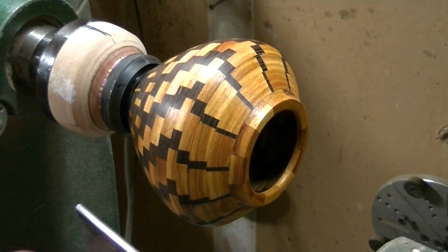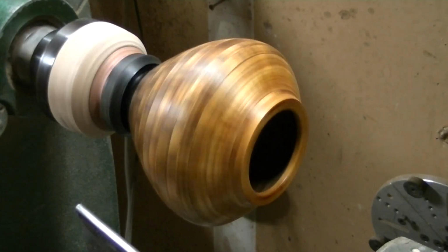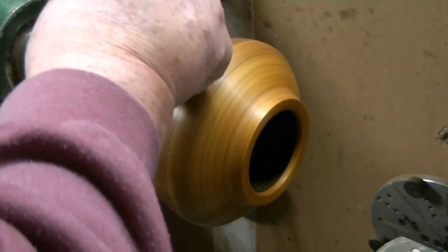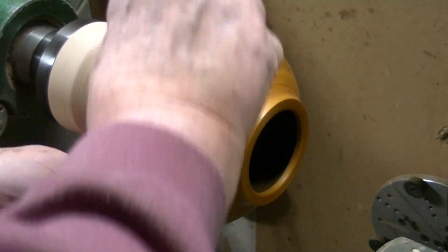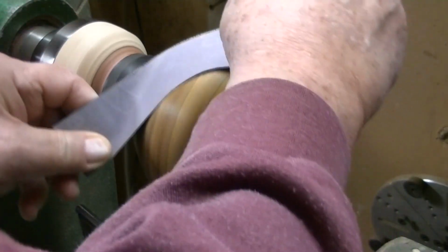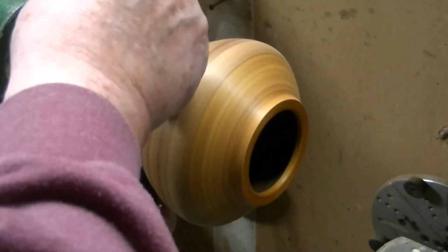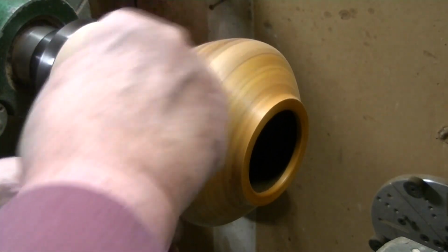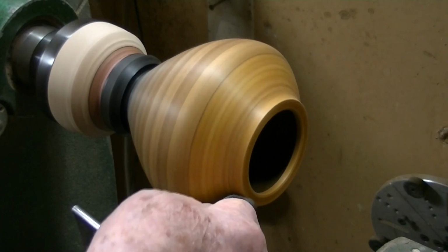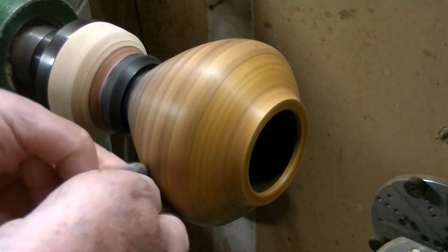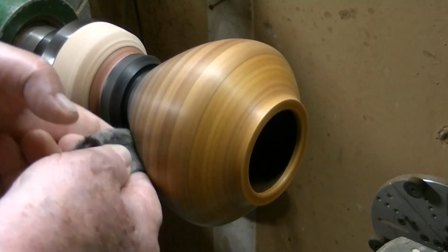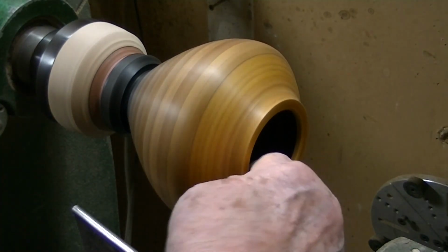Well, after that dries, it goes back onto the lathe again. And I'm going to take my 120 grit, 180 grit, 220 grit sandpaper and sand this back down to the surface again. What I'm doing is allowing the finish to fill into the pores of the wood and establish a flat base. So we need to do more sanding. Sometimes we don't want to, but we do. I'm finishing up here with a piece of 4/0 steel wool simply to give a really nice surface finish.